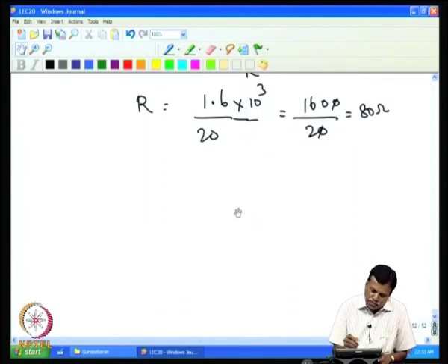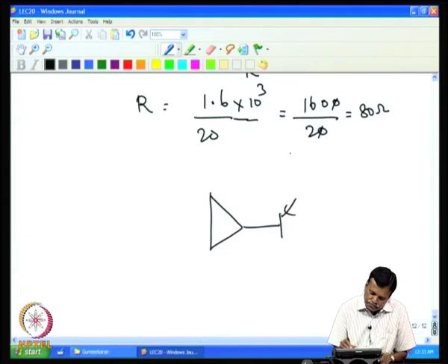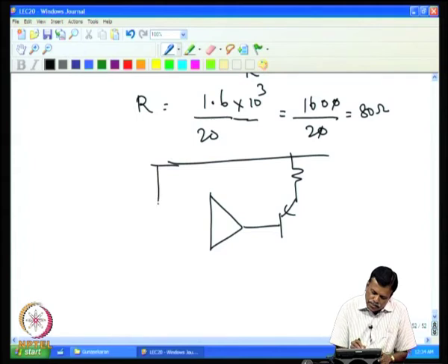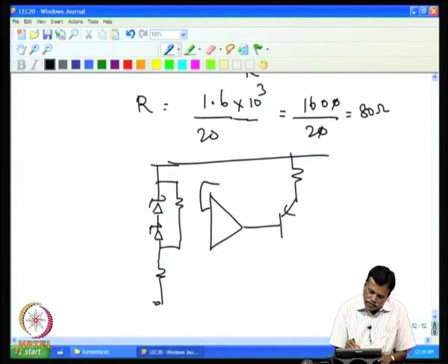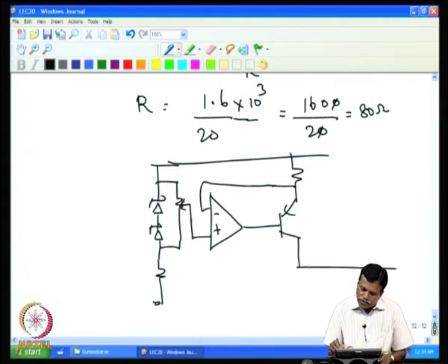Normally the variable resistance part is achieved in the following manner. If I look at the current transmitter part alone, it will be like this. We can have the 1.2 volt Zener and the potentiometer to go with that, and our 3-wire resistance is coming here.